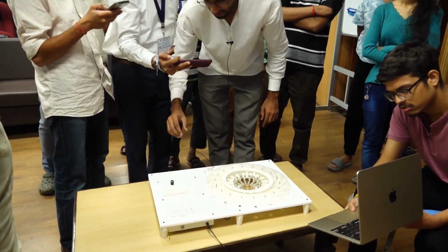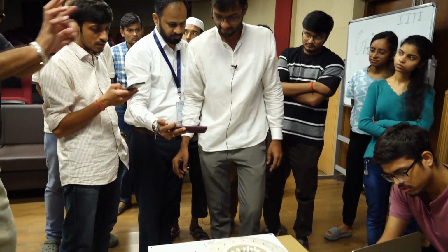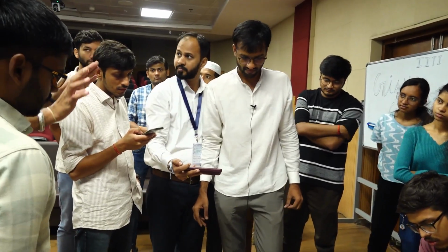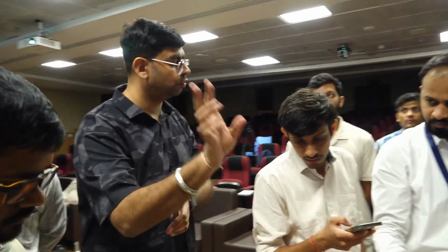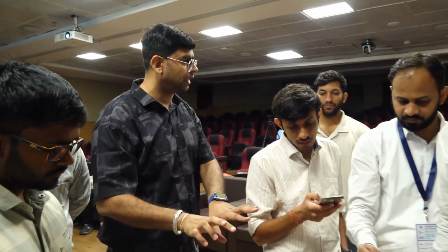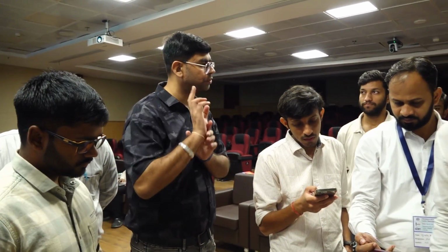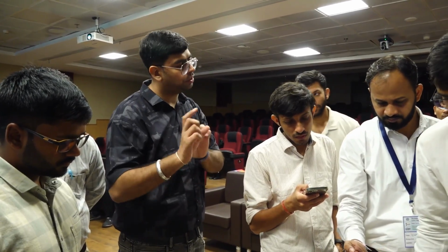Initial radius 30, you put the value at 60. So 30 mm to 60 mm means your pre-stretch will be 2. The other way is directly you have a stretch ratio, you put 2. So in the initialization you will get two options, either dimension-wise or stretch ratios.